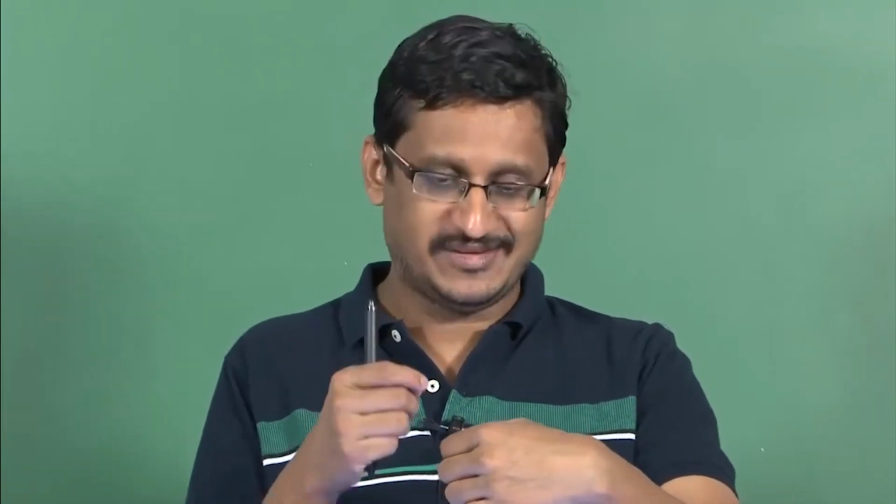So, I am assuming that this is a direct band gap material. It makes our life a little simpler, the efficiencies are better, and things are much simpler to understand without the involvement of any phonon, which would otherwise be the case for an indirect band gap semiconductor. So, in this direct band gap semiconductor, if I forward bias the photodetector, then I would have created an inversion, or essentially created a large number of electrons in the conduction band, because I am forward biasing this, and then I have these empty states in the valence band.